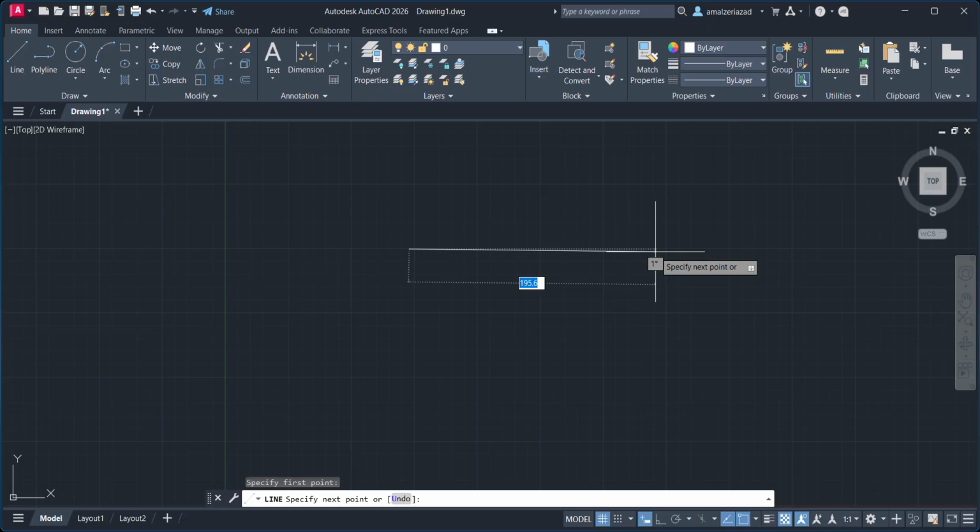If it is more, then still okay, you can go here. But the thing is, in AutoCAD, the dimensions will be driven dimensions. There are two things: one is driven dimension and one is driving dimension. Driven dimension means you can't change the value. Once you create a line, suppose I created a line of 200, the value of that is fixed.